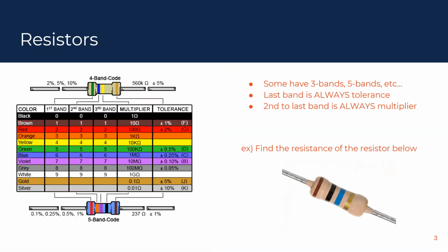First, resistors are manufactured elements that are color-coded. Typically, they're wire-wound, carbon film, or other materials, and they're color-coded to indicate the value of the resistance. This color coding is necessary because it is very difficult to write the actual numerical values of the resistance directly on the part. It's difficult to do it at low cost. So these resistors, some of them will have 3 bands of colors, some of them will have 5 bands, some have 4. The number of bands really just determines how to interpret them.